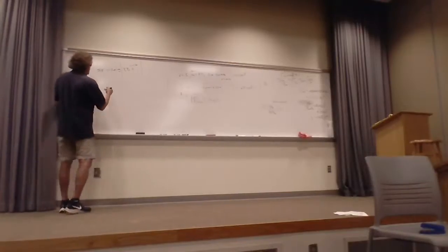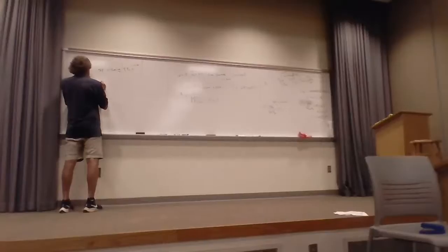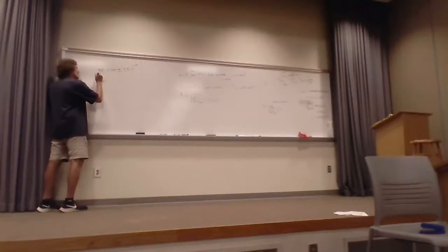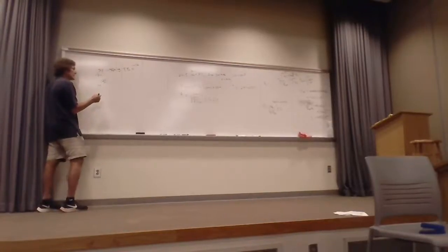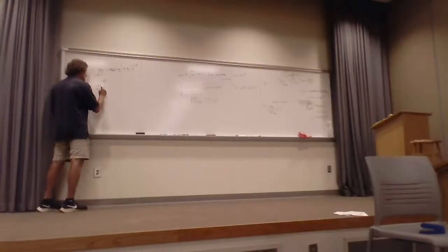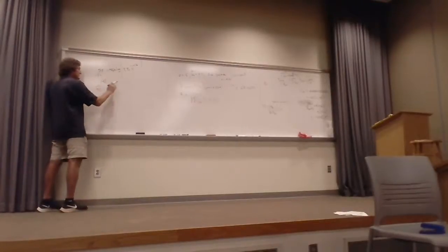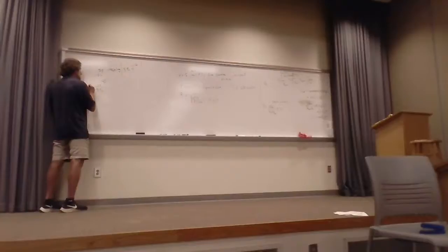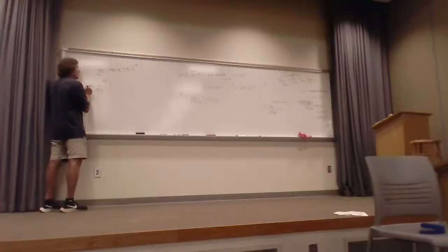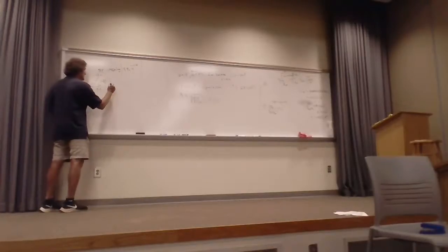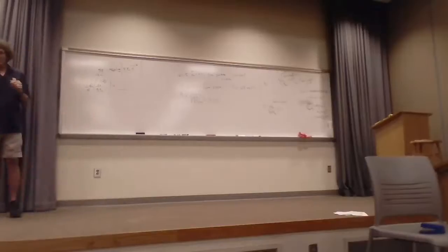So when we do this, we take 10 to the power of minus shielding effectiveness divided by 20. Let me tell you what I'm doing. First, I divide by 20, put a minus sign, so I get rid of that. Then I have to take everything to the power 10. Then I divide this by tau 1, tau 2. And then I have to take the natural log of both sides. So I take the natural log of this, and then I divide by minus alpha, and that's going to be the thickness. Do y'all follow me on this?